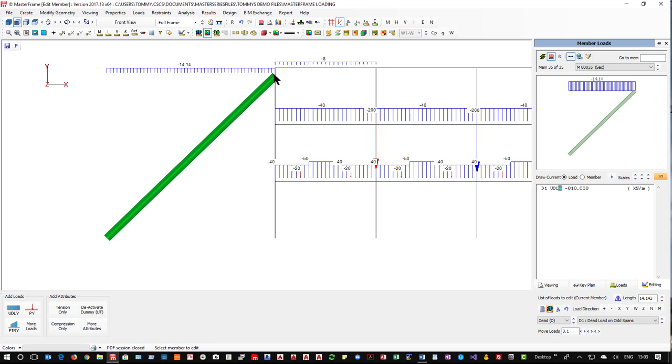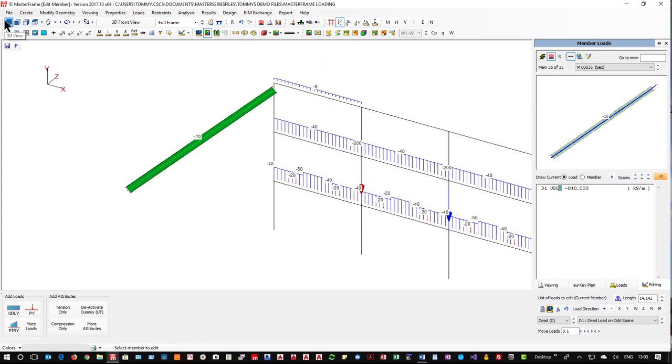So I have a member that is 10 by 10 coordinates, so 14.14 meters in length. So you'll see that the W load gives me 14.14 as my total intensity per meter, because it's converted it by the slope. Whereas normally we work with an x-axis load, which is over here, just drawing it in this direction instead of over here. A y-axis load, as we thought, and even a z-axis load, which is along the member, but it's still only going to be 10. So that's out of plane and hard to see in this case.